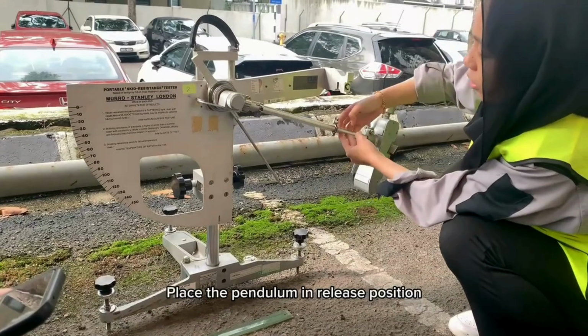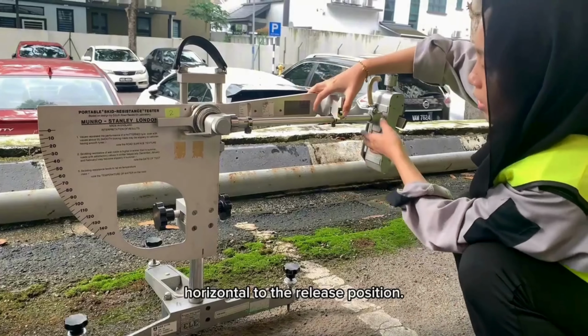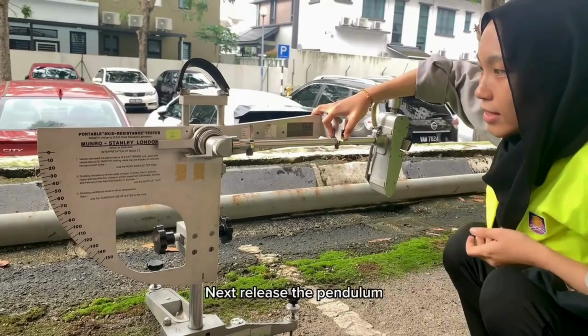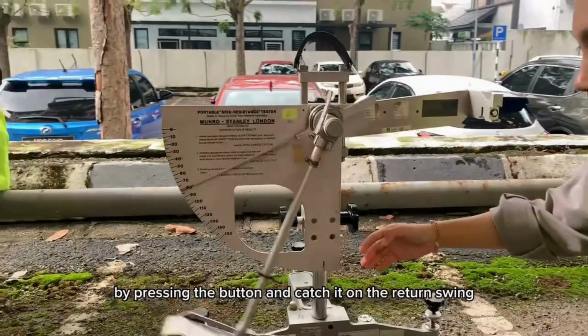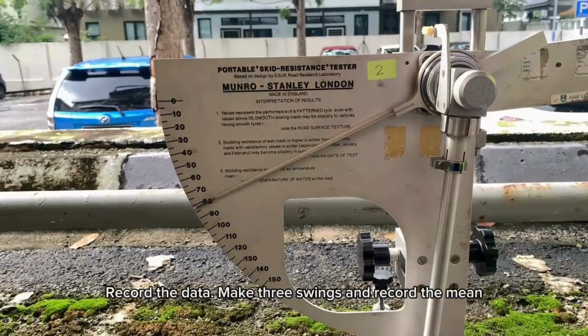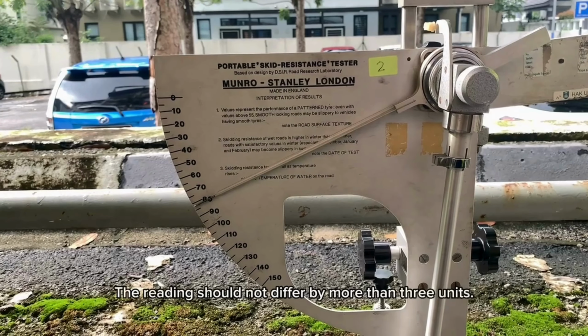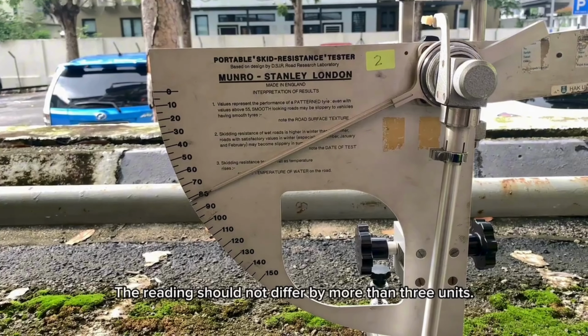Place the pendulum in release position and drag the pointer arrow horizontal to the release position. Next, release the pendulum arm by pressing the button and catch it on the return swing before the slider strikes the pavement surface. Record the data, make 3 swings and record the mean of the successive readings. The readings should not differ by more than 3 units.